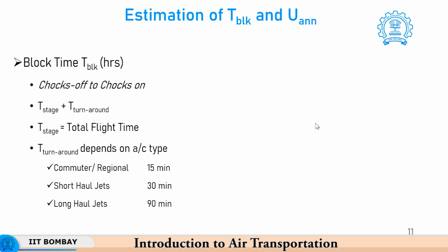Many a time the turnaround time is also a function of how much time is needed by the brakes to cool down after a very harsh and heavy landing where the brakes have been deployed. Sometimes it has been seen that these brakes become red hot and there is no way to cool them immediately except just waiting for normal cooling with the ambient conditions.